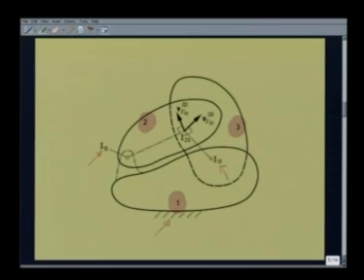Now, let us say that Aronhold-Kennedy theorem is wrong. That means, the instantaneous center I23 need not lie on the line joining I12 and I13, and let us assume it is at this location, I23 prime. Now, if I23 prime is the relative instantaneous center between body number 2 and 3, then it must have the same velocity whether I consider it to be a point on body 2 or a point on body 3.